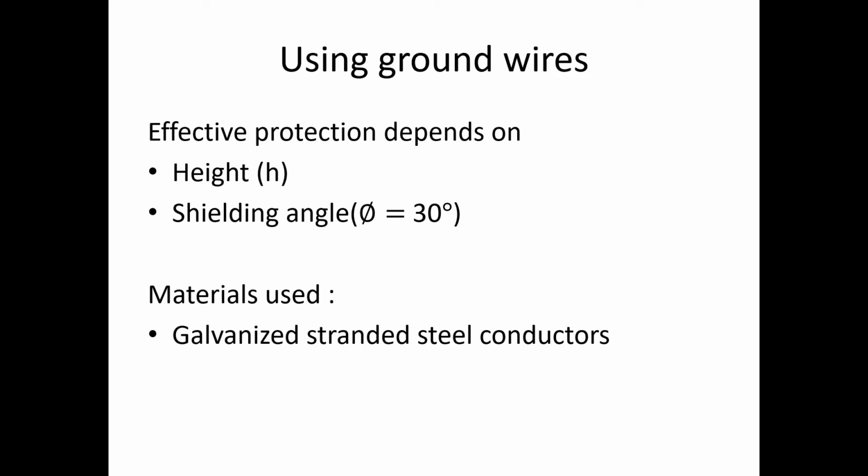What considerations should be kept in mind during the selection of a ground wire? While choosing a ground wire, you have to give more importance to mechanical consideration rather than electrical, because mechanical strength is very important, such as stability, reliability and so on.